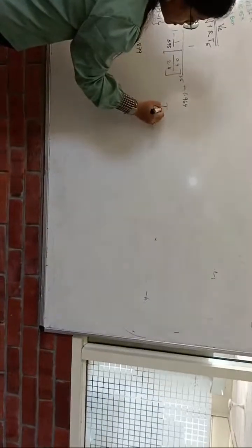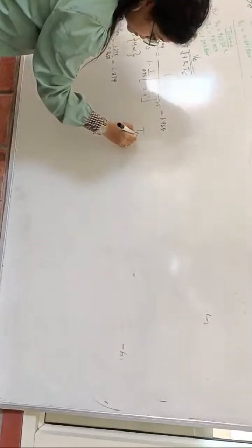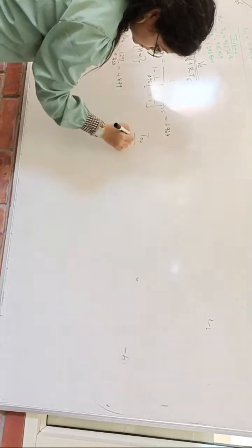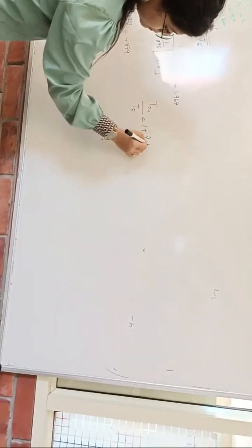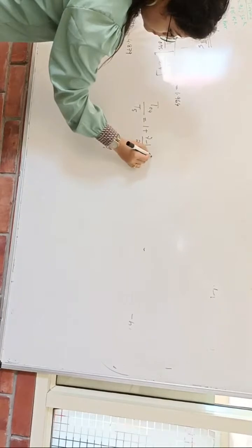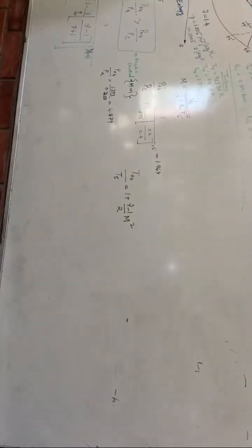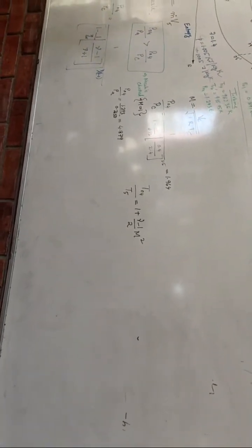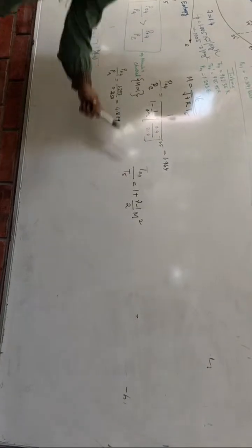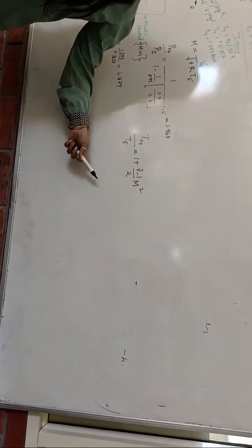Now, in the starting of this problem, I said that this is a formula. This total to static isentropic relation will be utilized both at the exhaust and at the inlet part, on both the diffuser and the nozzle part.